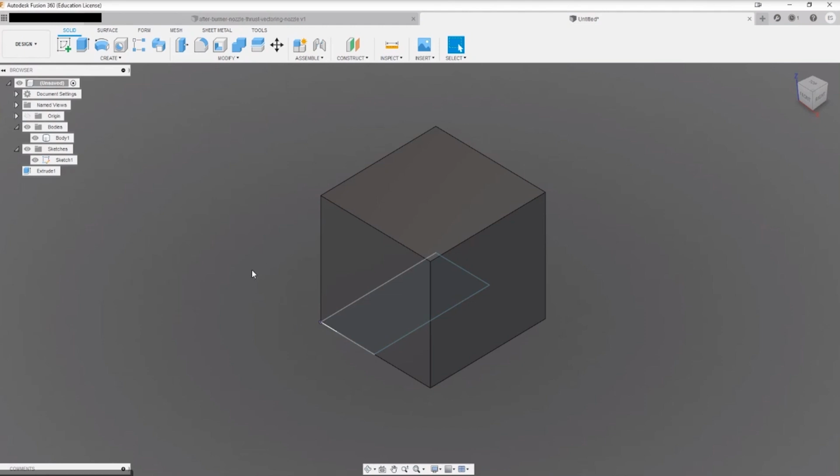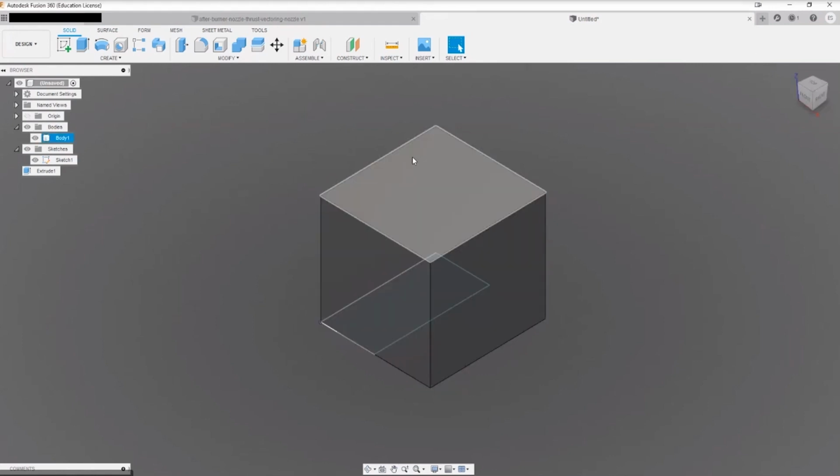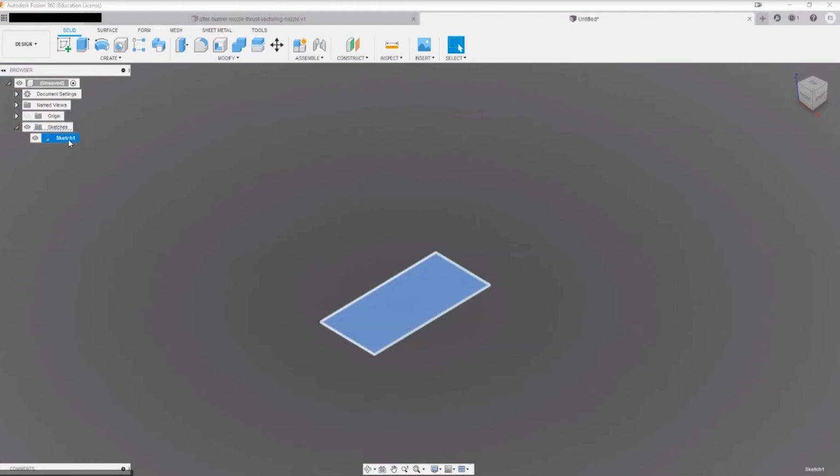Now, this is great if you're doing something relatively simple, but when you've got something super complex and you're working with multiple components, you don't want the software suddenly doing things on its own that you haven't sanctioned, all right? Secondly, it'll actually get in the way of you trying to delete parts because they were referenced somewhere in the history. Believe me, I've been using the software for 2 years. It's not something you actually want to bother using for multiple reasons. So just make sure you switch that off, and you've saved yourself quite a lot of time and effort in that respect. Okay, so I'm just going to get rid of that.